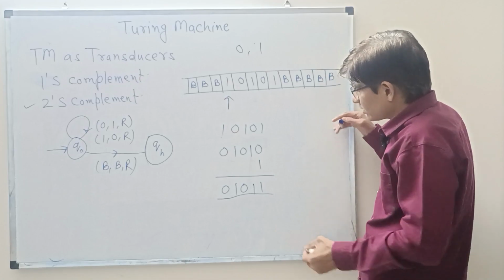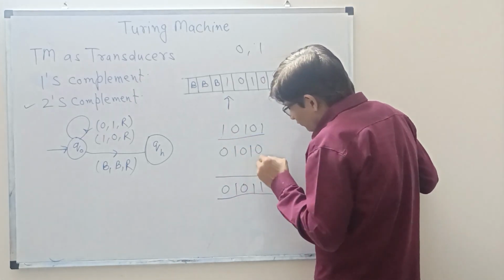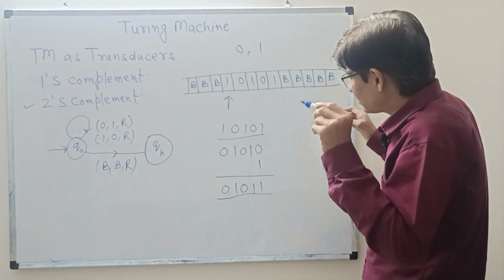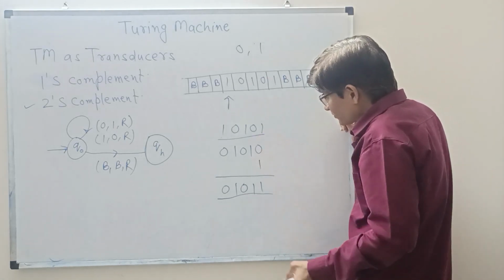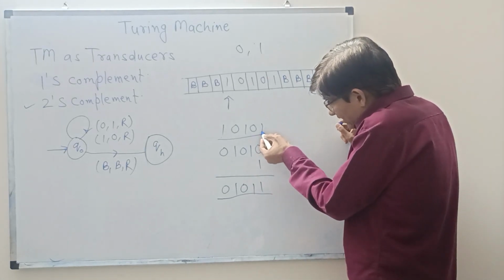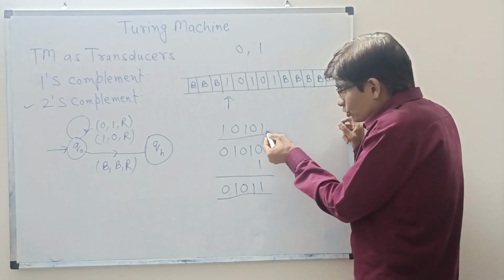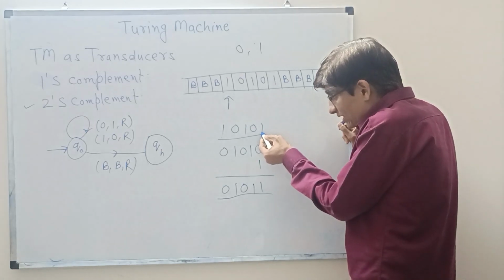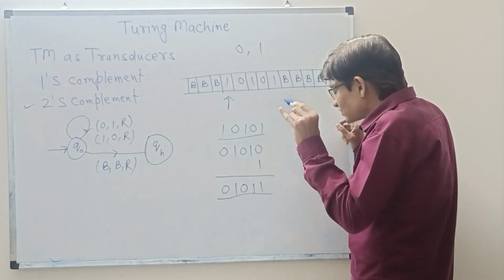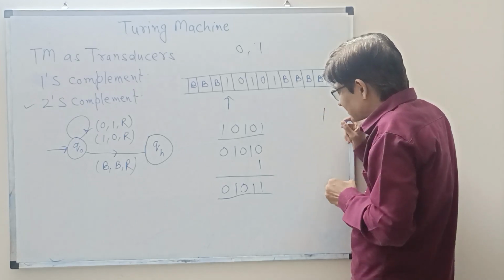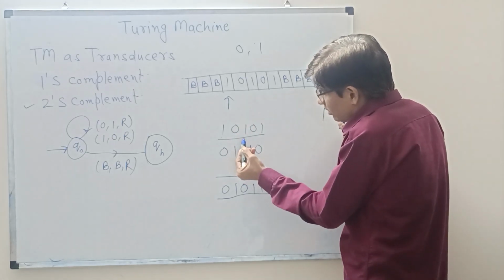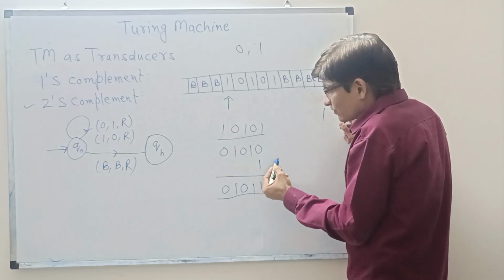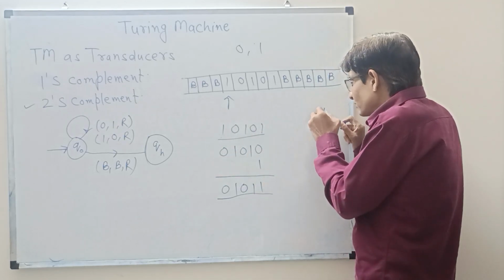So for this particular number, if I want to calculate the direct binary 2's complement of this binary number, I will start from the right hand side. As no zeros are there, we are directly getting 1. So the first one we will leave as it is, and remaining all bits after the first one from the right hand side, we will invert.